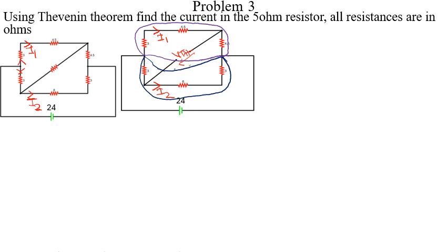So to write two loop equations for the purple one, for the first one, for I1, we can say 24, that is the voltage source, is equal to the sum of voltage drops, 3I. We realize that all these resistors are in series, because the same current I1 will flow through 3, 4.5 and this 4.5.